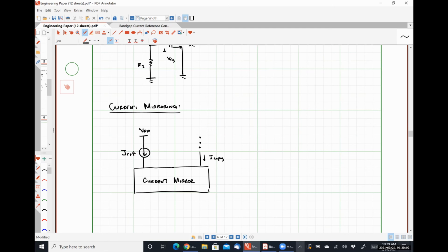And we can use current mirrors to make multiple copies of that same reference current, so that if we have one stable source of a fixed current, we can apply that exact same current all over, or as many times as we need, through a larger microelectronic circuit.